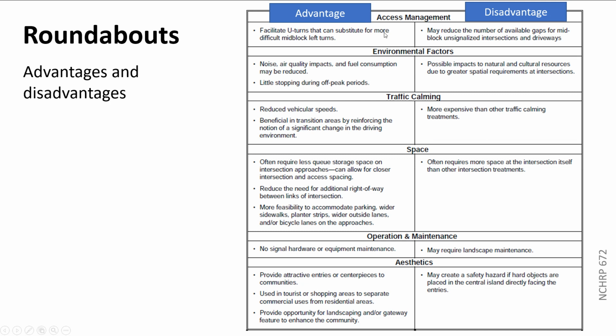So in access management, sometimes we'll want to cut off. We've talked before about the functional limits of an intersection, and we don't like having driveways within that functional limit. Or you may want to put a median down the center so that people can't cross in that area, which is safer and reduces conflicts.